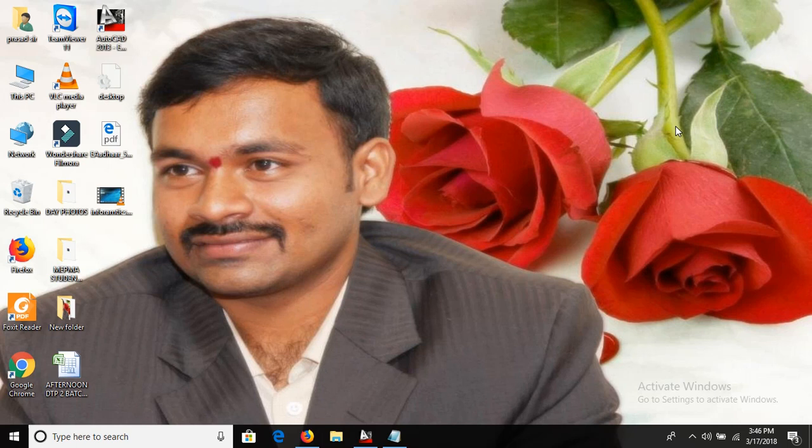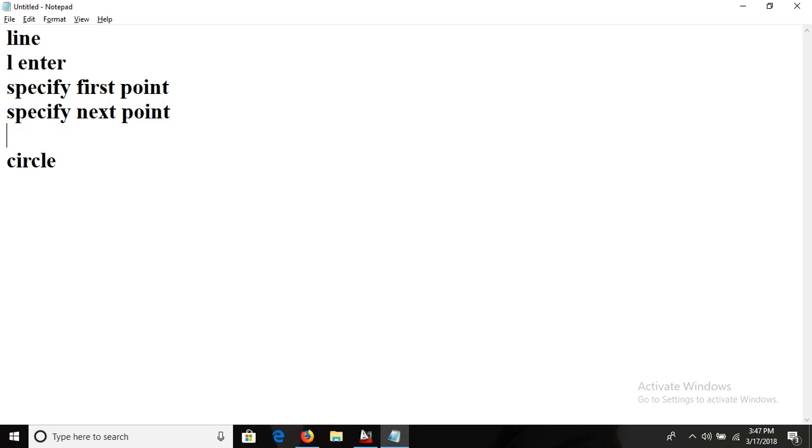Okay, today I'm going to discuss lines and circles. I'll be talking about only lines and circles. Look here, the line and circle commands. For the line command, we already know how to do it: type L, enter, and specify the first point. That's very important. Then specify the next point, and it continuously keeps asking like that. When it's complete, we need to press Escape.